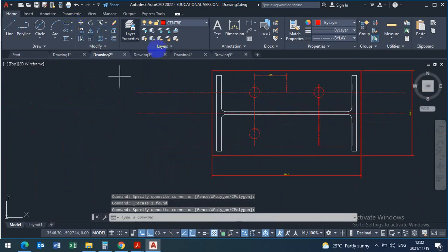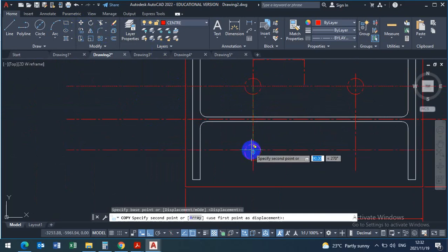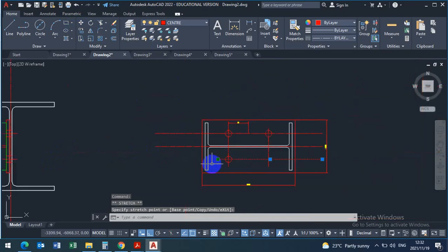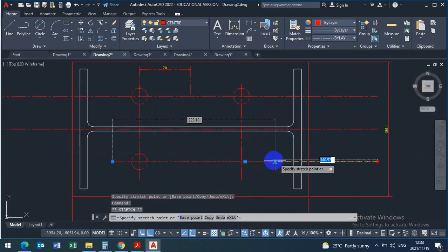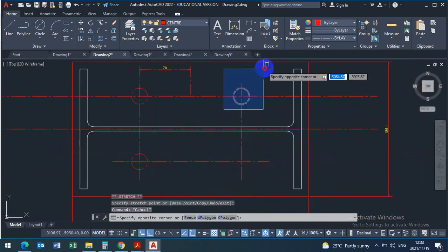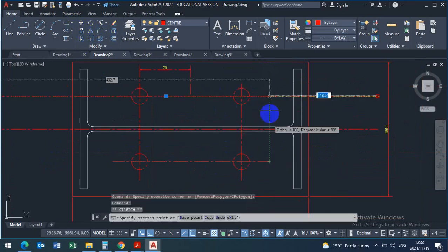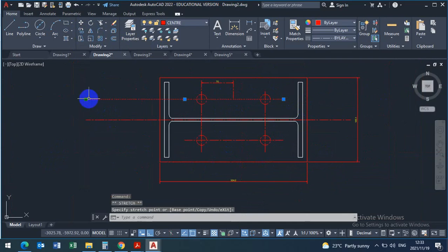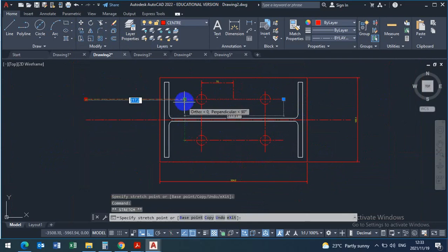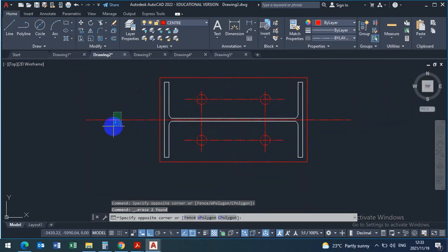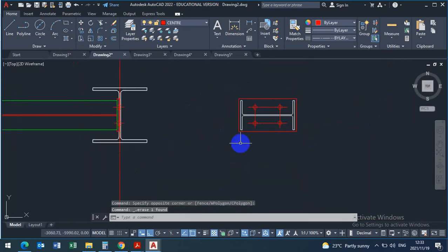Can copy the center line. You need to always have center lines on there, but must be trimmed somewhere here. Don't go out. I wonder where the circle has gone. Copy. Okay, dimensions I'll remove for now. We'll come and dimension later. We don't need this center anymore.